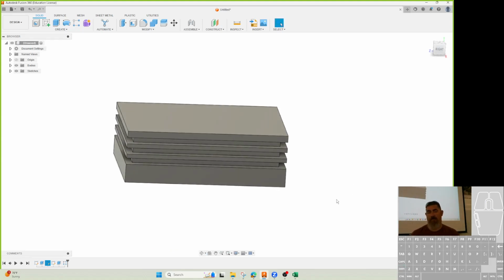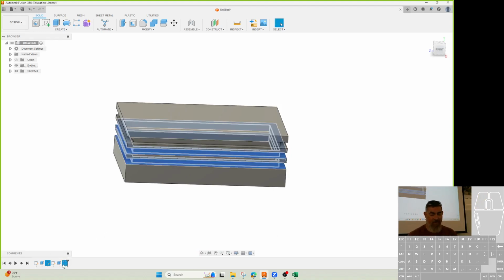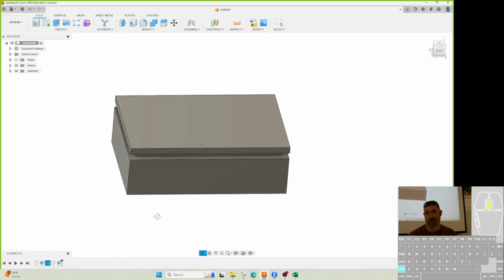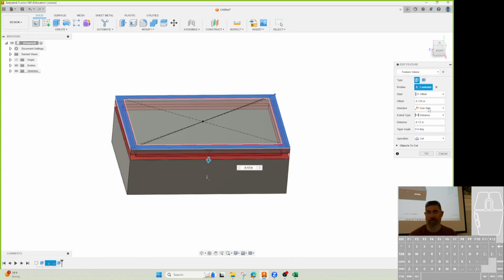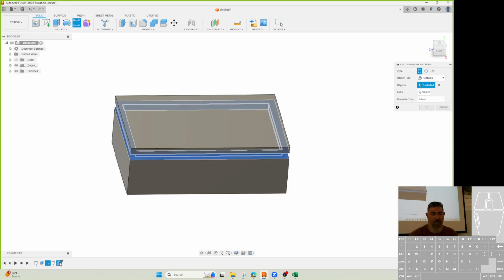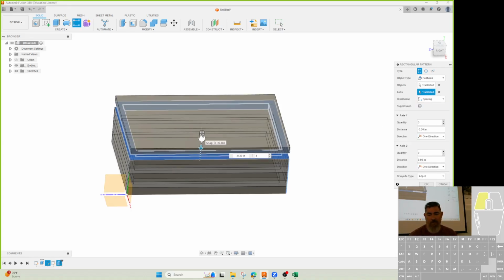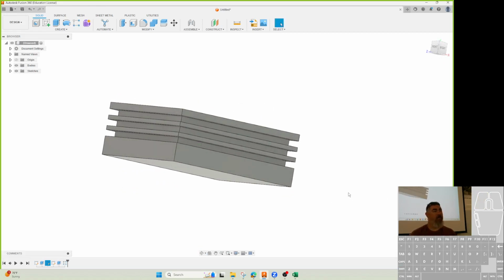Did you repeat that? I missed it. So I did that ring just like I did before. I created a sketch on the top, and then I extruded it with an offset plane, so that way it's down below the surface. Now I can just do a rectangular pattern of that cut, tell it where to go, tell it my spacing, and now I've got multiple cuts there.